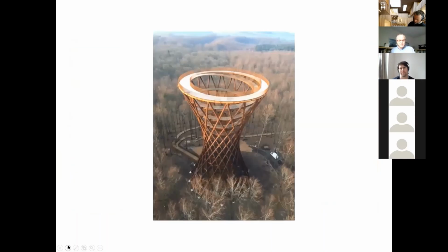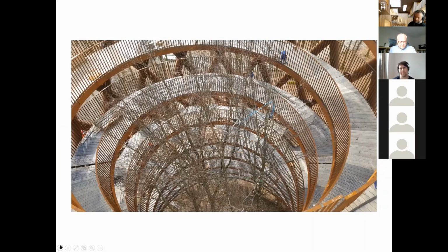Safety, just to mention about that. Our erection method was developed and planned carefully with great attention to the safety issues, of course. We paid great attention to fall down of materials and tools, and as a consequence of that, the inside part of the tower was blocked from access during the erection period. We presented our erection method to the Danish safety authorities at an early stage and had a good relation and cooperation with the authorities during the erection period. We had no accidents.